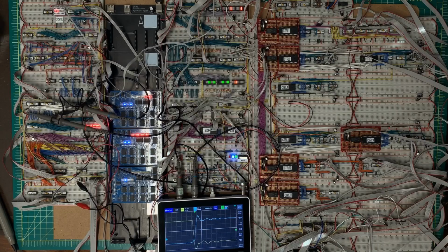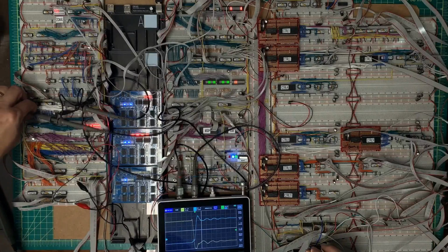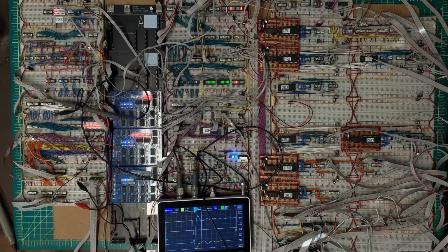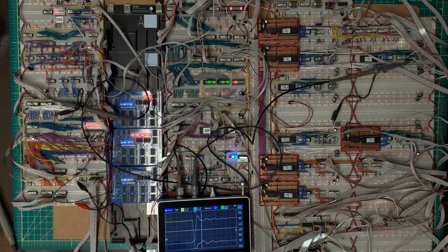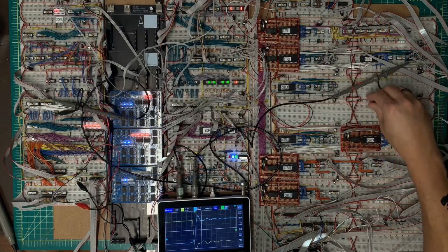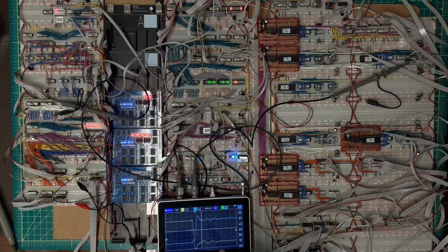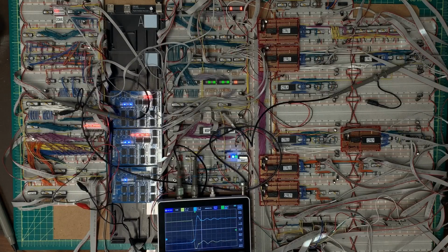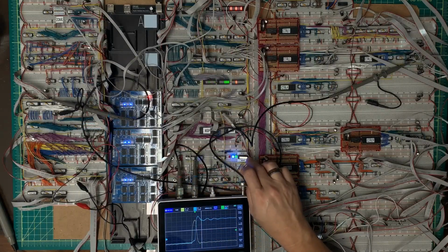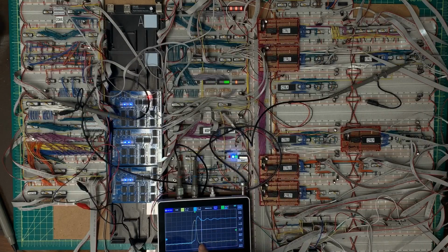So now I need to compare my latch against my R1 load. R1 load is control ROM 3 bit 1, and that is the shaped signal. Now I want to trigger off of channel 2 the rising edge, because that's when the latch is taking place. So let's see what that does.